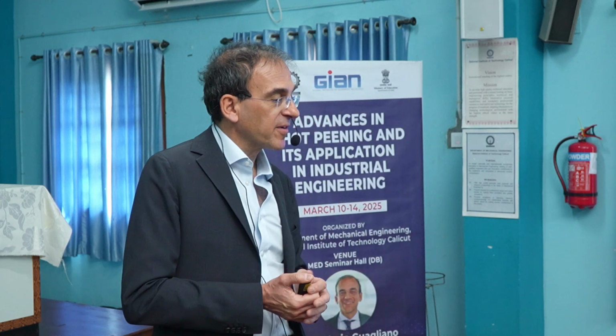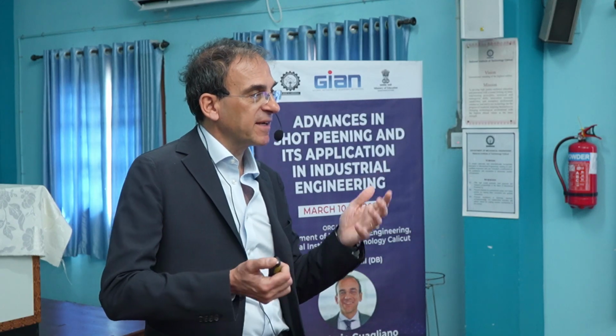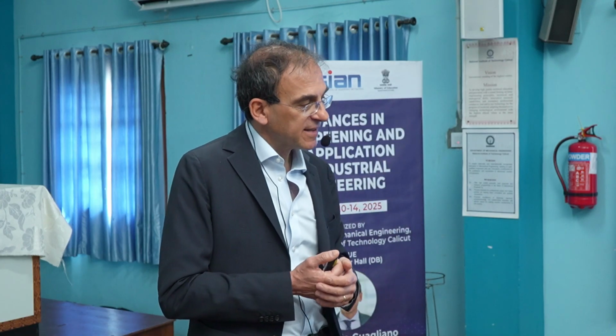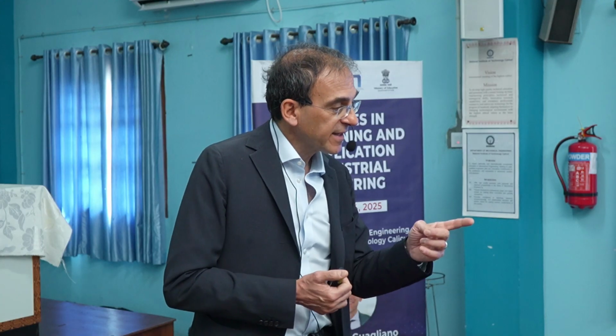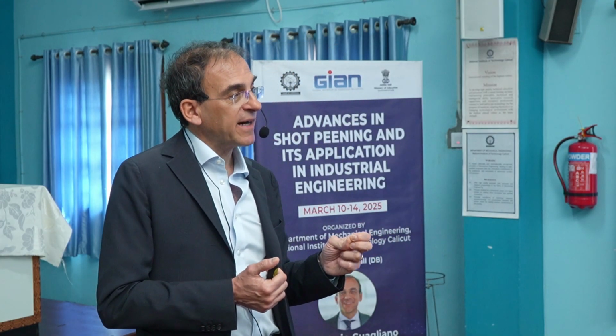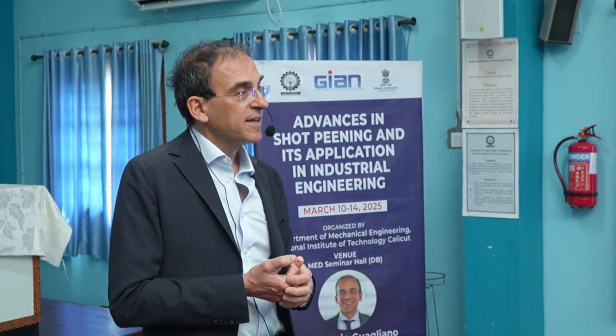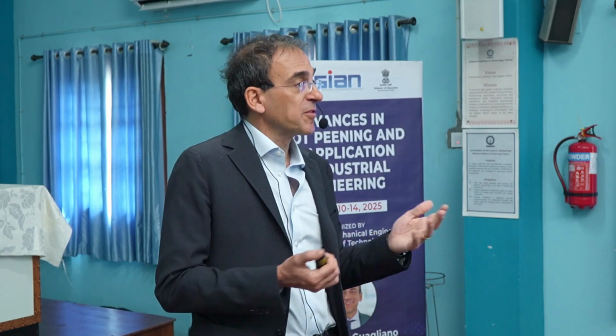That is why we can cover just selected areas by means of the accuracy we can get by using air peening, a gun, and a controlled movement of the gun. As we said, this is good for accessing difficult geometry, intricate geometry, not all of them, but many intricate geometries, and small parts. We can use different intensity on the same part if we need different intensity, and this can be done by changing the pressure of the compressed air during the process.